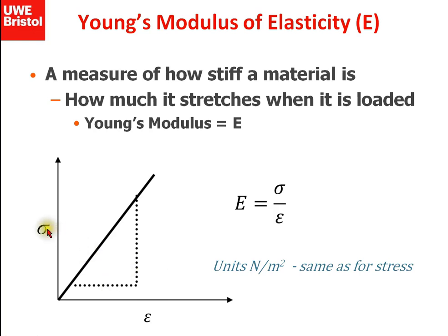So what happens is that if we plot a stress strain plot for a piece of rubber that's quite short and we're trying to pull it apart, and we compare that to another experiment where we repeat with the same material but a longer piece, we end up with the same stress strain plot. That's why we're going to look at materials in terms of their stress strain plots. More force being applied, more extension, and we get a fairly linear growth for most materials.